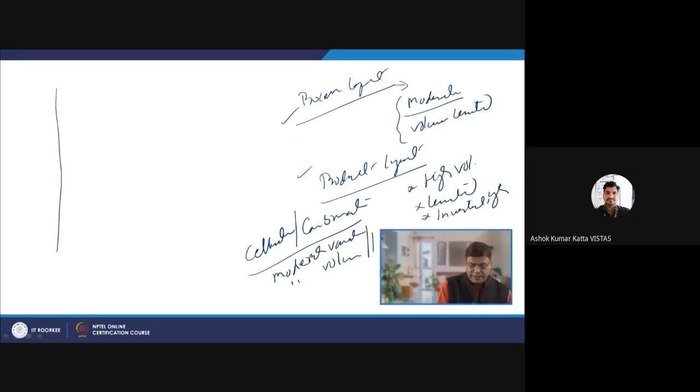So, if we see in terms of the total cost which comes out from the process layout and the product layout, as far as the initial cost and the variable cost, for the process layout, say the fixed cost is less, but the variable cost is high. So, total cost will come like this. This is the case of the process layout.